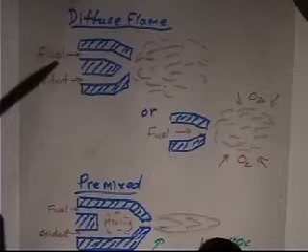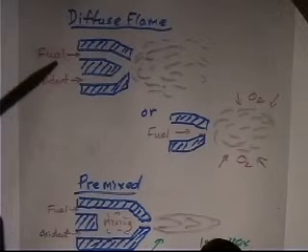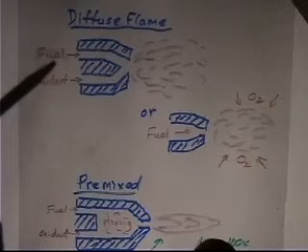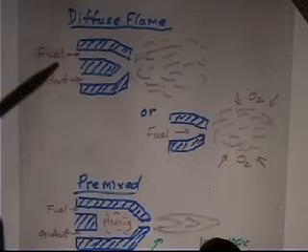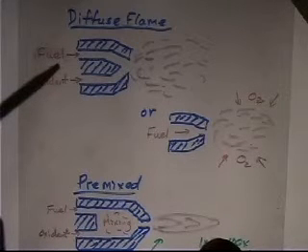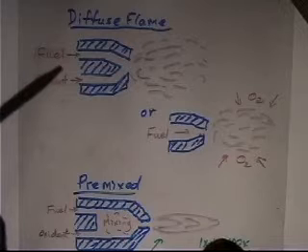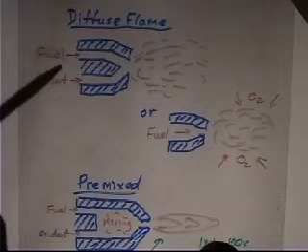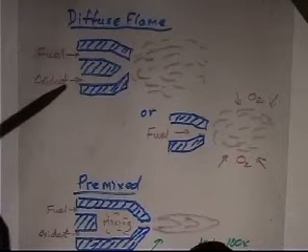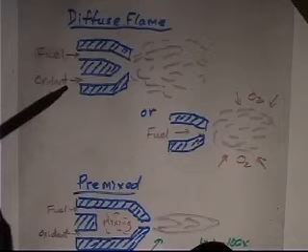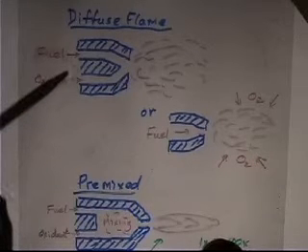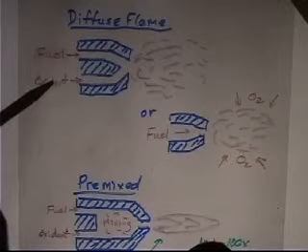I mean, there's all kinds of conditions that go into flammability ratings. But nonetheless, there is a significant difference between acetylene and methane and propane. Propane is even more difficult to get an explosive mixture in air because it's an even more complex molecule than methane, and so its flammability limits, I think, are like 8 to 11% in air. They're fairly narrow.